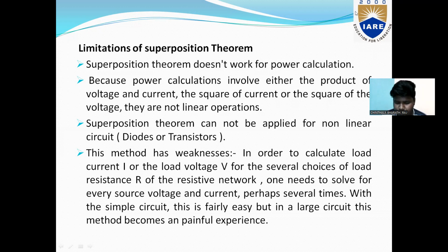Another statement of the superposition theorem is: in a network containing linear impedances, where impedance does not change with the flow of current, the current generated by the energy sources flowing at any point is the vector sum of the currents which would exist if each source of EMF was considered separately, all the other sources being replaced at the time by their internal impedances.